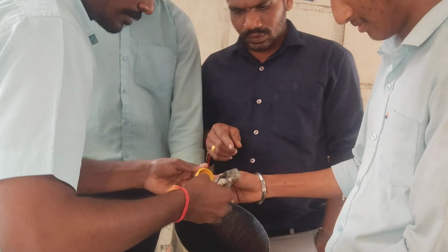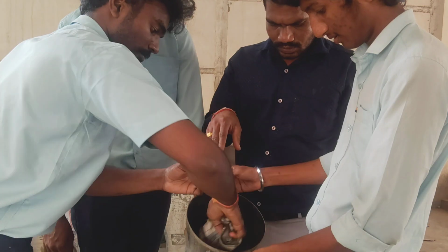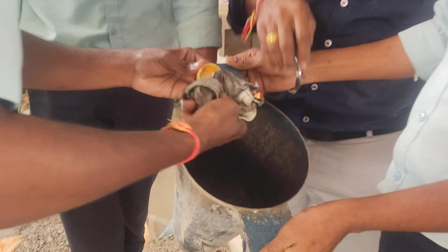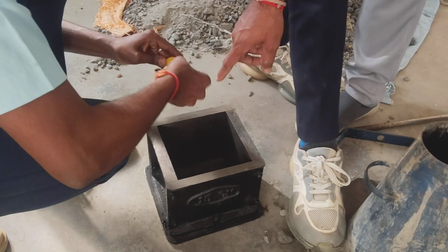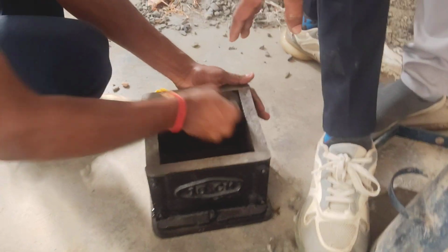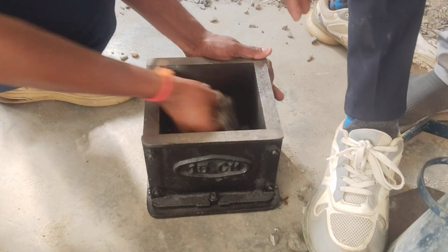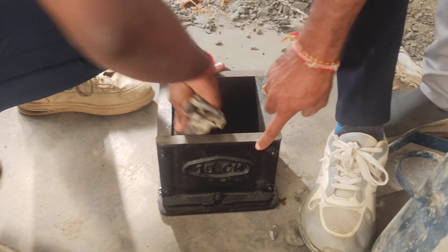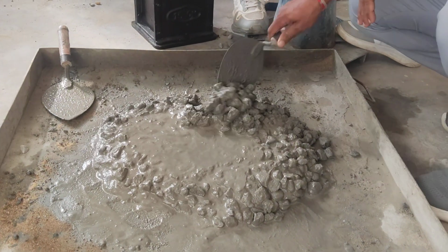Before using the slump cone, we have to apply hydraulic oil internally for smooth functioning, because the concrete is non-stick. The base is also used, and the oil is smoothly applied on the internal surface of the mold. After the slump test is completed, we cast the cubes, and before that, oil is applied inside the cube mold. The cube size is 15 centimeters by 15 centimeters by 15 centimeters. Next, we are ready, having applied oil internally, and the concrete is completely mixed.